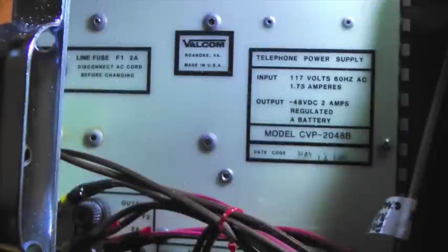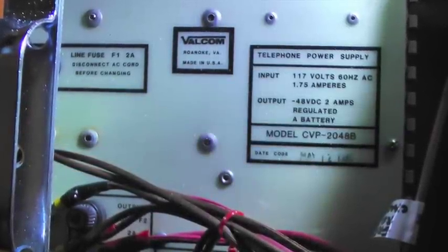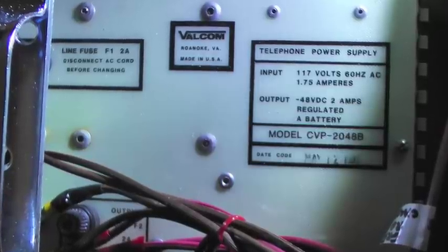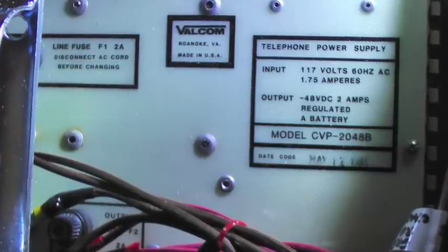A 6-second ringing cycle, having a cadence of 2 seconds of ringing followed by 4 seconds of silence, is provided by a Pylon ringing interrupter. This emulates the standard one-ring arrangement that would be provided to this type of connector in the central office. The alternating ringing current is superimposed over a 48-volt direct current supplied by my Valcom 48-volt DC power supply. The DC component is necessary to trip the ringing upon call answered.